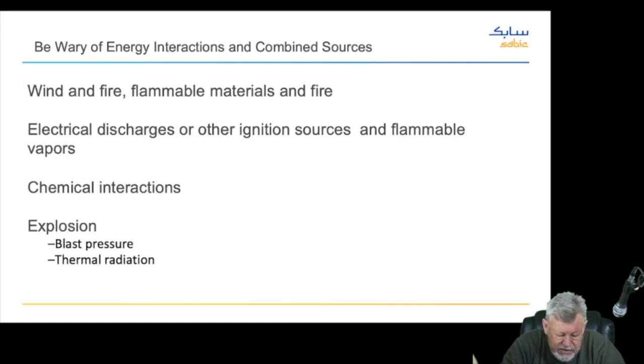The next slide tries to highlight the fact that even though a single hazard, let's say the wind, is not that strong, so it's not a big issue, suddenly I am lifting a big steel plate. And because of the area of the steel plate and the medium force of the wind, now I have an issue. Also, if I have fuel or flammable materials and a heat source, and I add wind to it, then suddenly the hazards working together have a greater effect. They present a greater danger.